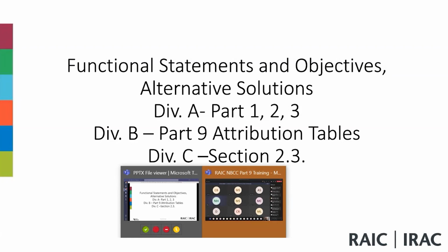Yeah, but the item after that, which talks about the fire resistance and combustibility in relation to occupancy, height, and supported elements, has a table after it which talks about the fire resistance ratings for structural members and assemblies. I just want to know, when we're talking about floor or ceiling assemblies here, is it talking about only wood construction, or is steel construction included?